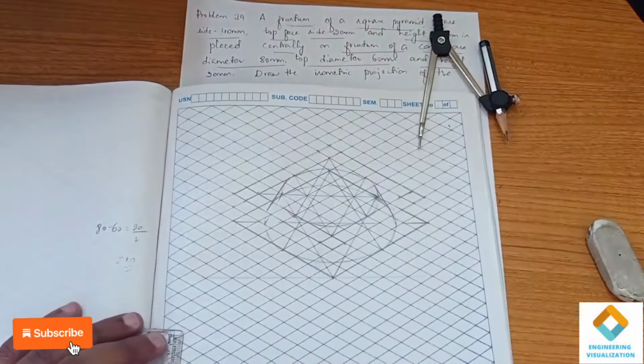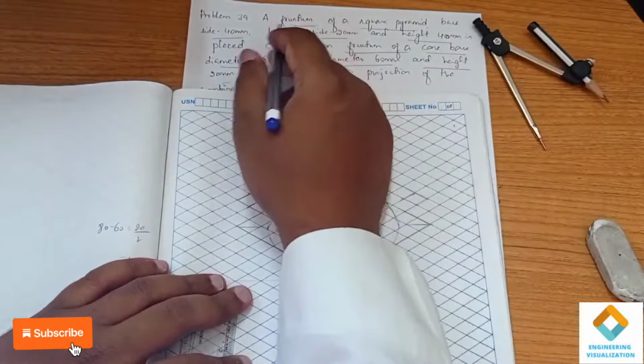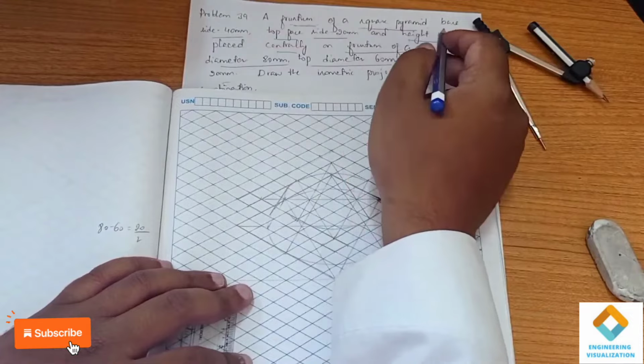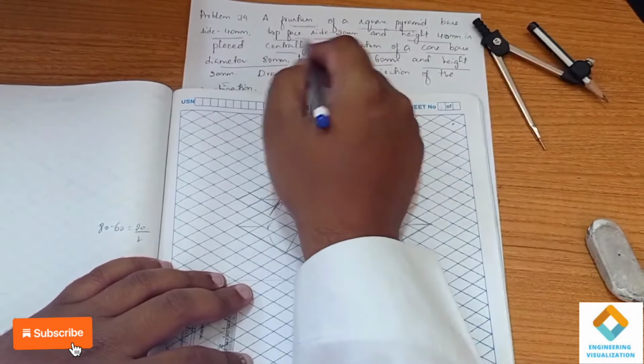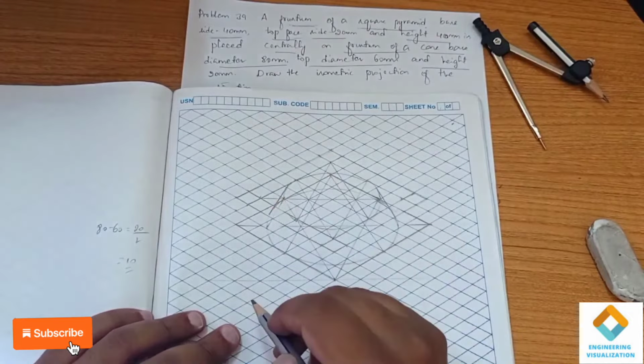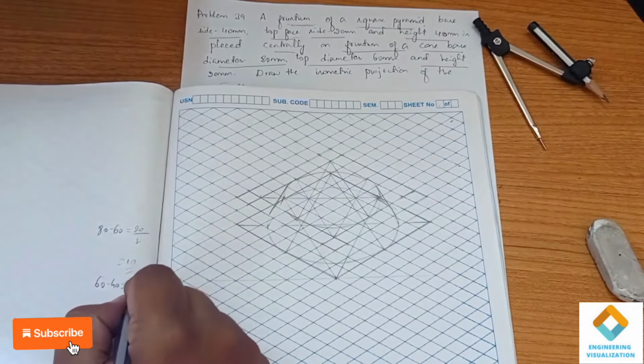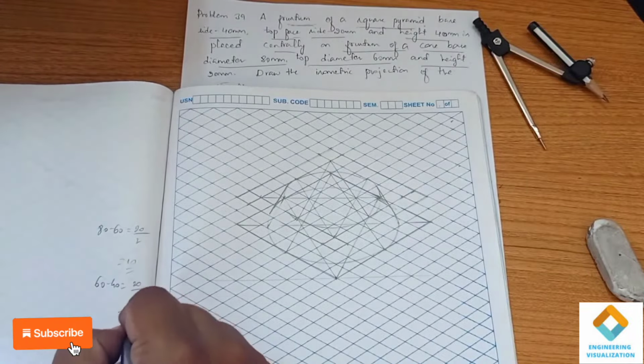So above it we have to construct the frustum of a square pyramid. So it is having a base of 40, but we have a top face of 60. So we are subtracting 60 minus 40, it is 20. Either side means it is 10.